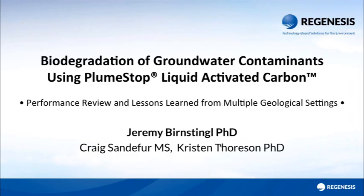Would PlumeStop work for chromium-6? Actually, yes, it would. We haven't tried it with chromium-6. Chromium-6 can be treated on activated carbon, and there are probably many people listening who've used activated carbon pump and treat systems for chromium. Whether it's the best approach is another question, but theoretically it can be used. I would compare it to a number of other different treatment technologies, but the answer is yes, it can be used for chrome-6.